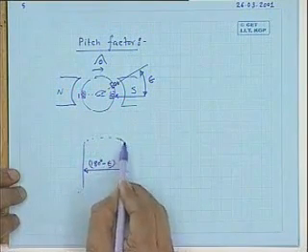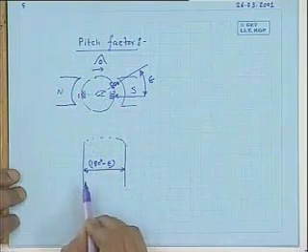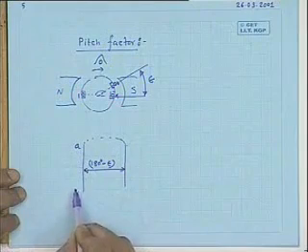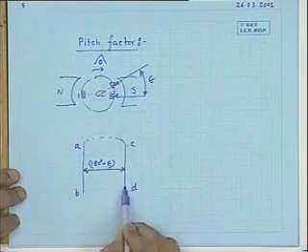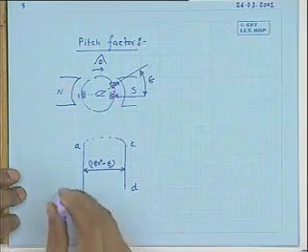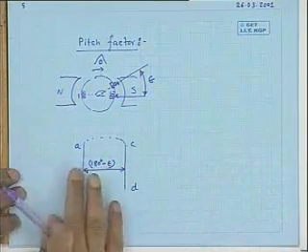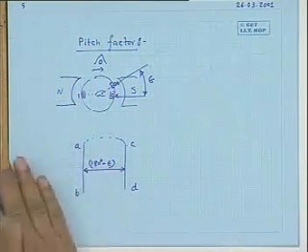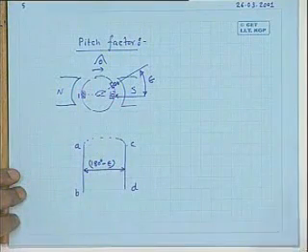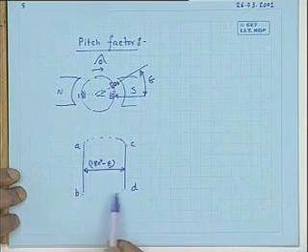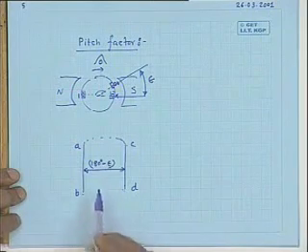It is like this. Now this coil is joined at the back, because it is a coil after all. It will have its return path. I will call this side A, B, this side C, D. Imagine a magnetic field traveling perpendicular to this B distribution, with relative speed. Let us assume the coil is stationary and a flux distribution is moving from left to right. I want to find out the resultant voltage between D and B.